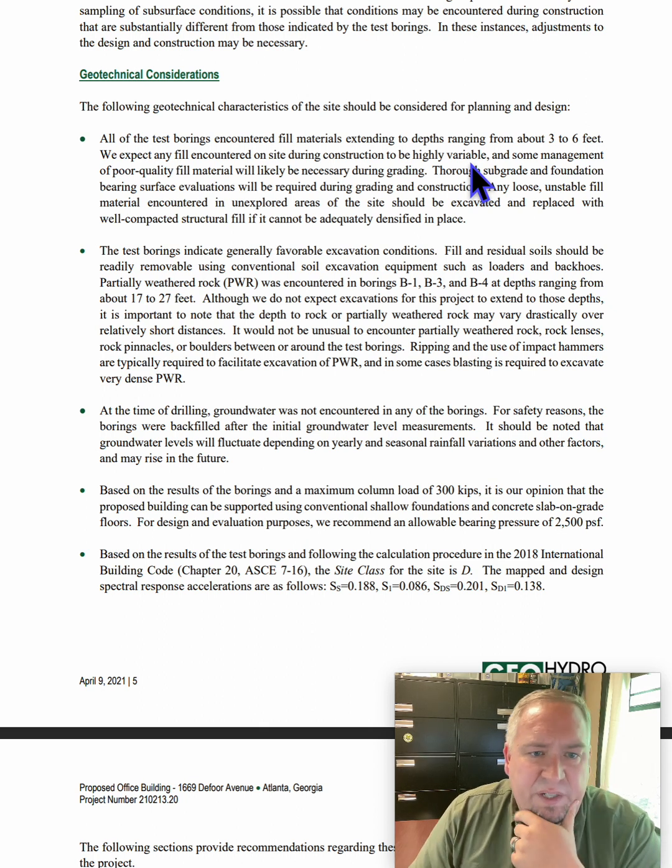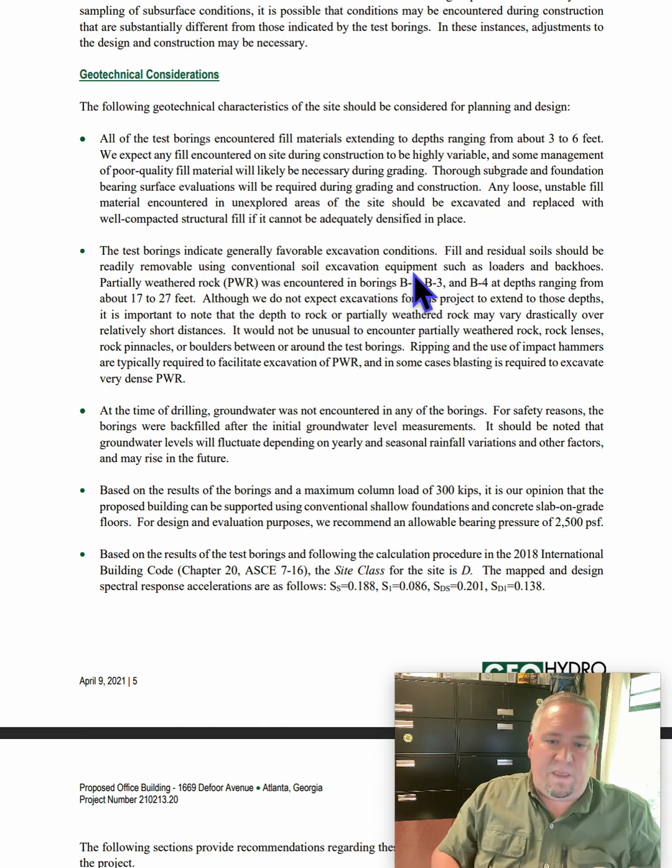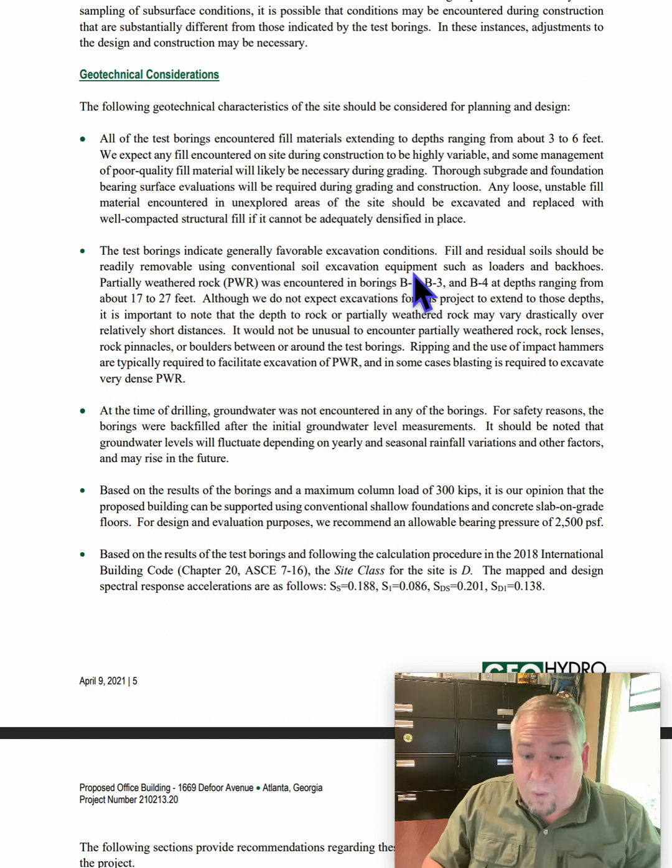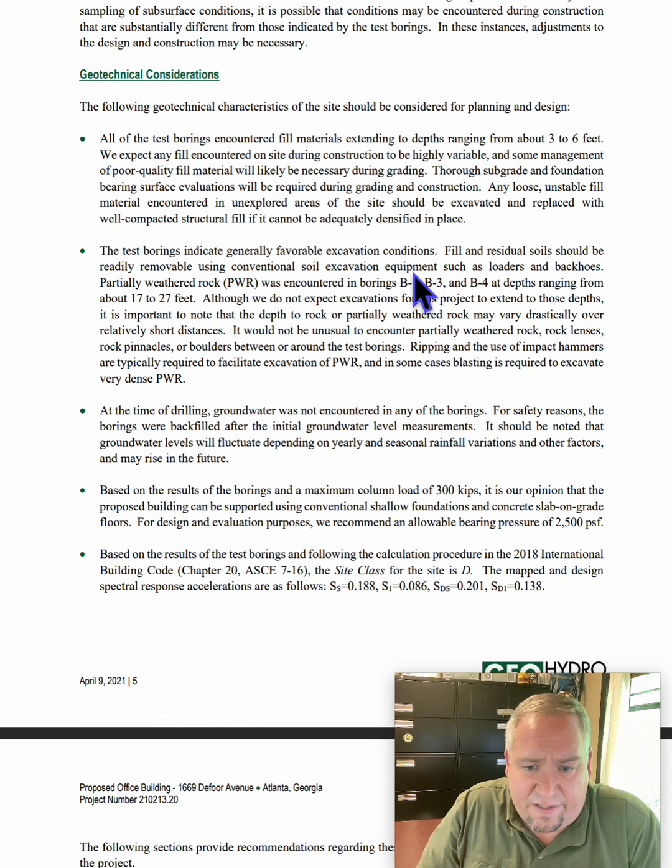Let's skip down. I'll let you read that. The test borings indicate generally favorable excavation conditions. Fill and residual soils should be readily removable using conventional soil excavation equipment. So they're saying, hey, these residual soils, these have been here for a while. We don't foresee anything that you'd have to get some big giant excavator. Just the standard stuff will work fine. And these guys are in our business, so what they say is pretty good here.